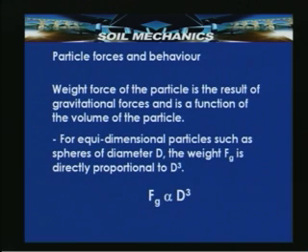Weight force of the particle is the result of the gravitational forces and is a function of the volume of the particle. For example, for equidimensional particles such as spheres of diameter d, suppose you represent a particle as a sphere of diameter d, the weight Fg is directly proportional to d cubed. So, with an increase in particle size, the gravity force increases.